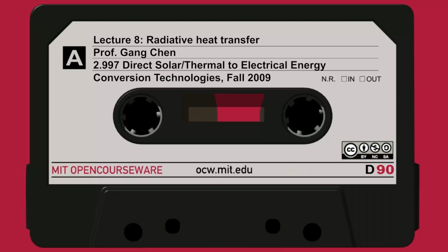The total emitted power of a surface, normalized by surface area, is what we call the emissive power. So now if we normalize, the emissive power equals the intensity times the area, dA perpendicular to the intensity direction, so I have cosine theta and d omega integration. So this is still per unit wavelength. So that's the emissive power.